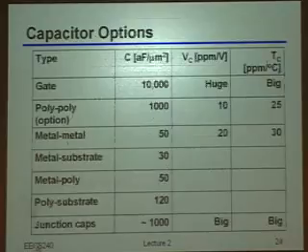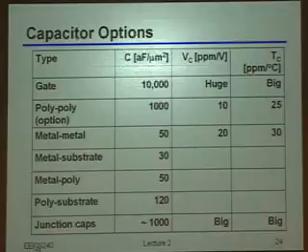Okay, so we spent quite a bit of time thinking about this very simple structure. It turns out that's going to be quite useful, because a lot of the considerations we talked about there will show up in the other types of capacitors as well. But much like we did with resistors, this is a table showing the different possibilities for how to implement capacitors. They range from something very similar to what we showed, the so-called metal-metal capacitor, metal-to-substrate capacitor, metal-poly. Sometimes we even have a so-called poly-to-poly capacitance, where they play some of the tricks you guys talked about. They'll make a thin layer of oxide or insulation between the two pieces of poly to try to get a higher capacitance density.